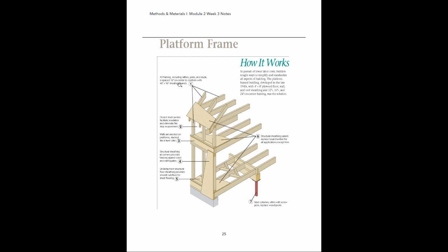And the frame elements, these are all standard, going to be spaced 16 inches on center. Okay, so that means the center point of each of these studs is going to have a standard dimension between them of 16 inches. Okay, so that's kind of the modern standard.